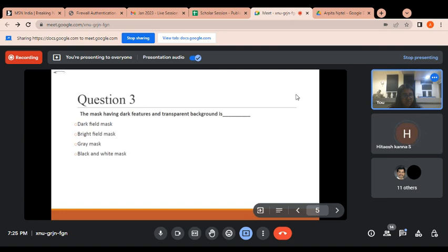If you want contact photolithography, then there is contact between the mask and the photoresist. There are three types of photolithography: contact printing, proximity, and projection. What type of process you use depends on your needs, and you are transferring the pattern from the mask to the photoresist. Then after dissolving and some processes, you get the pattern transferred from the photoresist to the desired device.